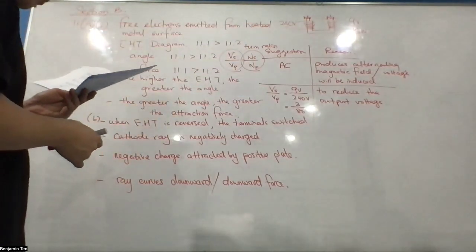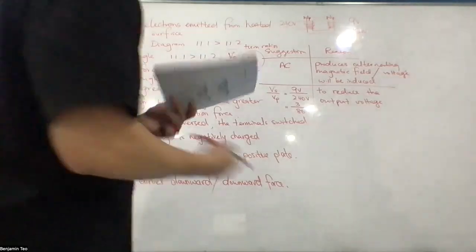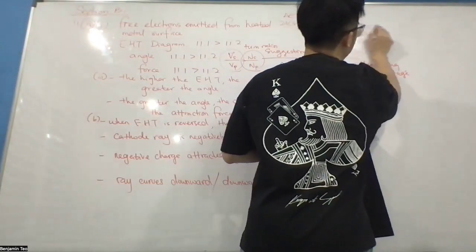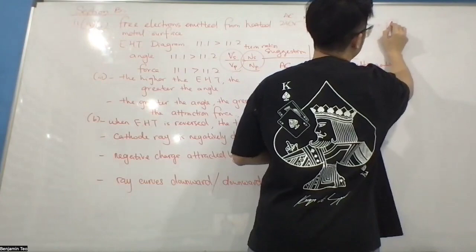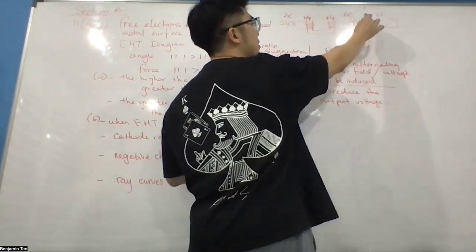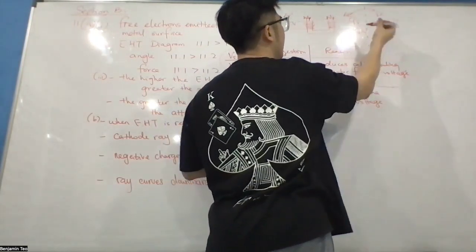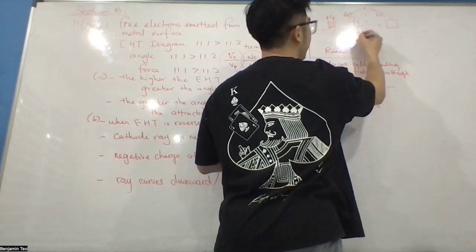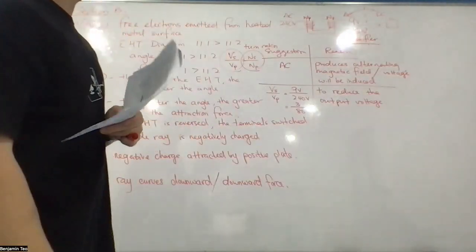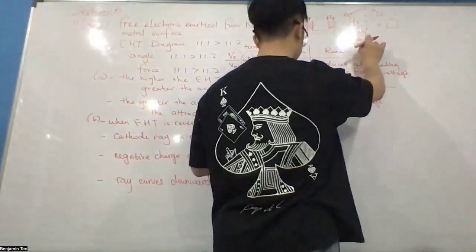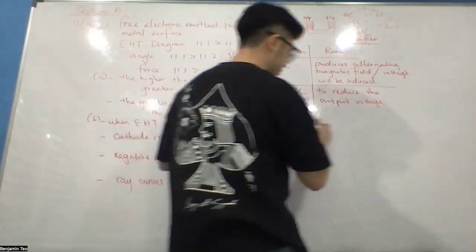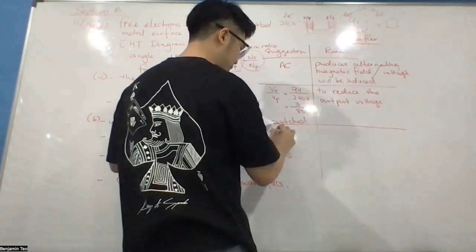Electronic components and number of components for the rectification process. Rectification: here is AC, so the current you produce on this side is also AC. When you charge your battery, the battery cannot accept AC, it has to receive DC. So in the middle you need a component that can convert it to DC, and that process we call rectification. So you need a rectifier to change the AC to DC. What is the component of a rectifier? The rectifier consists of 4 diodes.